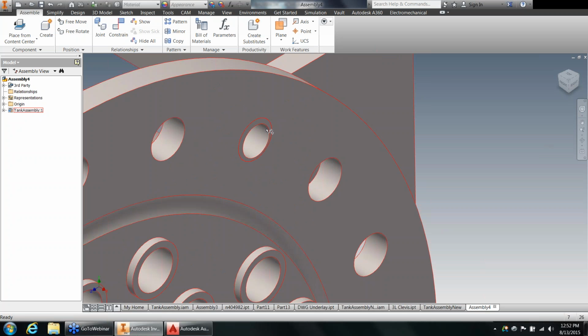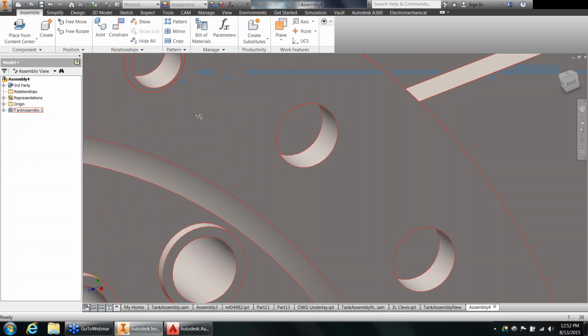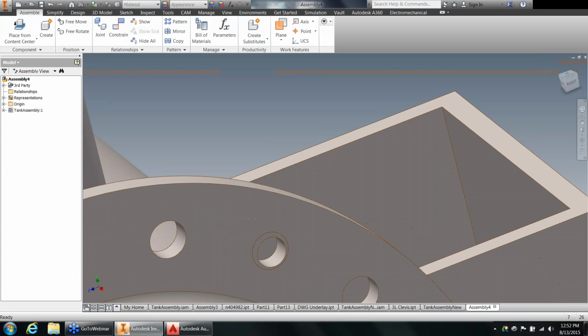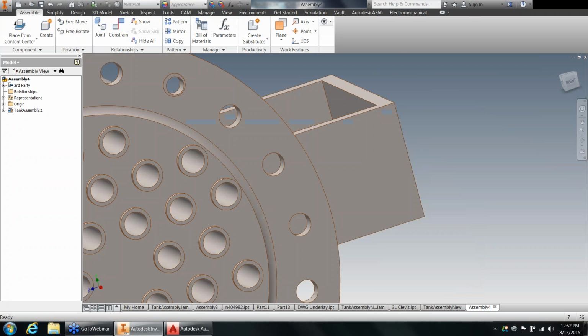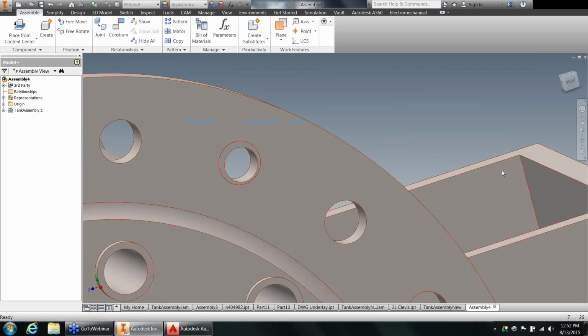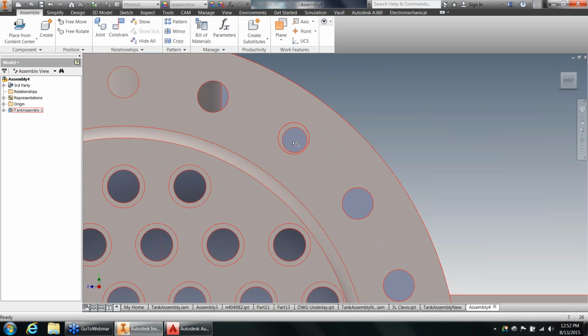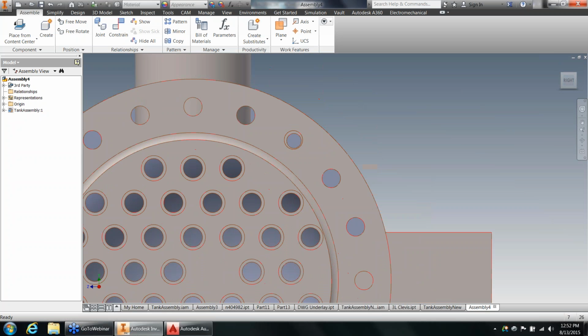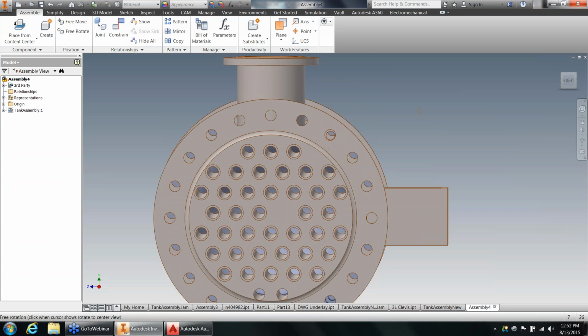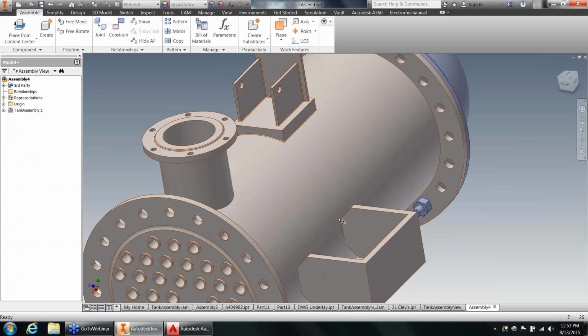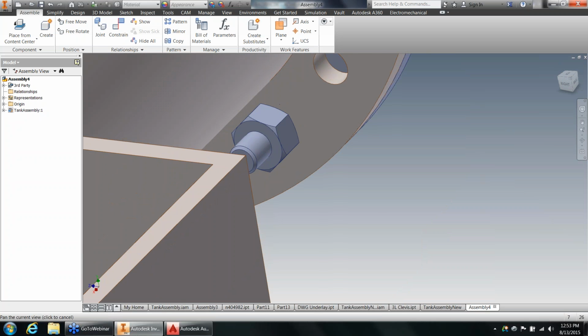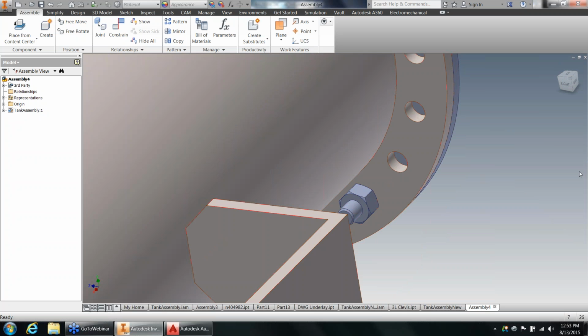Yeah. So it pulled something through for the thread designation, but it didn't actually pull real thread data. Yeah, I hadn't done this before, so I wasn't certain what the definitive was going to be on that part. What'd you do there? It's off kilter. So yeah, it looks like the thread information does not trickle across through the AnyCAD importation.